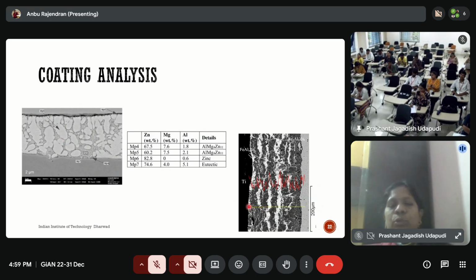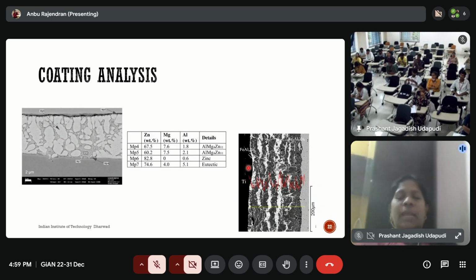What you can do is go for a line scan. In a line scan, you can select where to start and where to end, and you can select the particular element also. I am interested in how, in this particular case, titanium is distributed across the line. So this is the pattern of titanium across this product, whatever formed over the substrate surface.